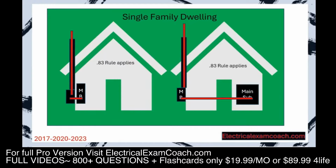So we're allowed to apply it on this one on the left for the whole wire. We use that table and size our wire based off the table. And the scenario on the right, for all of that wire there for the service itself, and then also for the main feeder, as long as that panel that it's feeding is feeding the entire structure. You would go to that table, do your cheat sheet, find your size breaker, slide over, and you'd be able to use that size wire.